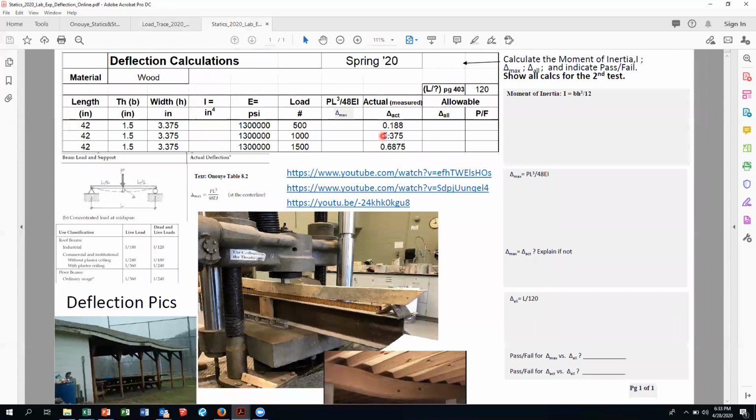And we'll show you these where now we actually had a measured deflection. We had the maximum deflection based on what it should be theoretically. Okay. And then we dealt with our allowable. So now we said L over 120. We only used a 2x4. So we'll play around with that. So that's about all I have for you tonight. Let me just check my, yeah, that's about it for tonight.